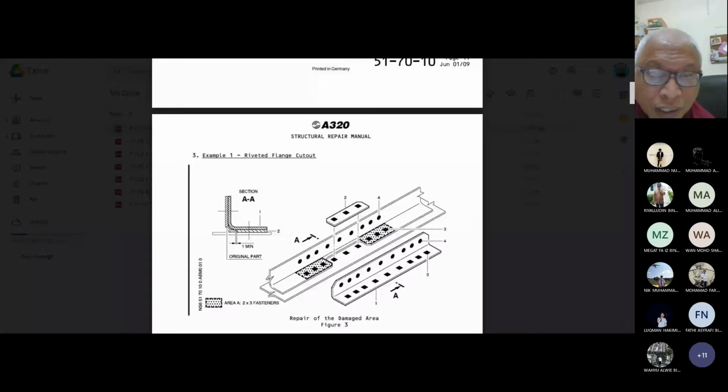Normally for large aircraft, we use all extrusion. For smaller aircraft, we do see this kind of form section because it's easier to form, and the thickness is thinner than the extrusion. Large aircraft have higher load, so they need to carry the load across, and they need thicker and more stable sections. That's why we use a lot of extrusion. Let's review the examples one by one, and then we go into detail on each.